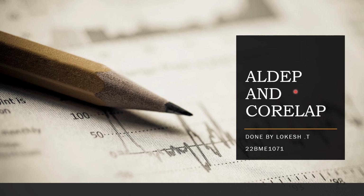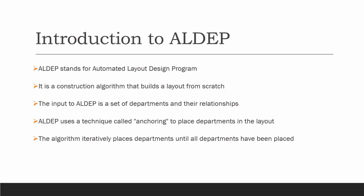Okay, we'll move to the ALDEP introduction. ALDEP is a construction algorithm and it stands for Automated Layout Design Program. ALDEP is a construction algorithm that builds a layout from scratch. This means that it does not require an initial layout to be provided. There is no need for an initial layout.